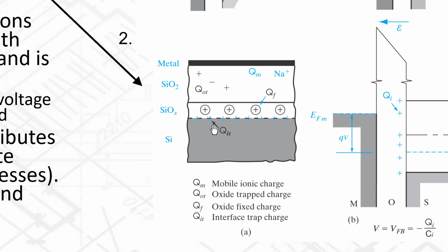And if you think about this, this was a really difficult problem to deal with when wet etching processes were used, because the amount of charges that would get buried in the oxide was very unpredictable. One day your water might be a little bit cleaner than the next day, and one day your transistors have a great threshold voltage and the next day they don't.